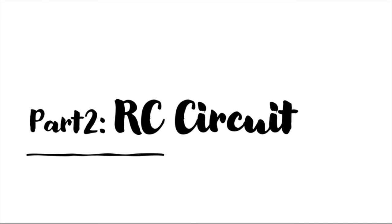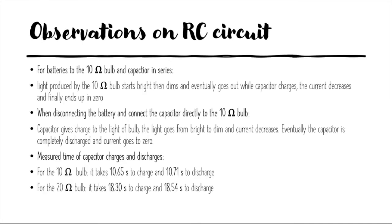The second section is the RC circuit. These are my observations on the RC circuit. For the battery connected to the 10 ohm bulb and capacitor in series, the light produced by the 10 ohm bulb starts bright and then dims and eventually goes out, while the capacitor charges and the current decreases and finally ends up at zero. When disconnecting the battery and connecting the capacitor directly to the 10 ohm bulb, the capacitor gives charge to the light bulb. The light goes from bright to dim while the current decreases, and eventually the capacitor is completely discharged and the current goes to zero.